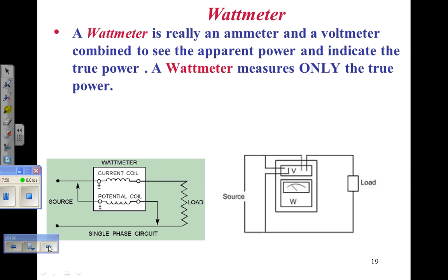Apparent power is whatever is coming in. When you get an Edison bill, it says watts, but it's a lie. They're charging you for every volt that comes in and every amp that flows in. That's called apparent power and is measured in volt amps. So if we're using 120 volts at 10 amps, how many VAs are we taking in? Somebody say 1,200. That would be incorrect. 1.2 kVA. K is 1,000. 1.2 thousand volt amps.